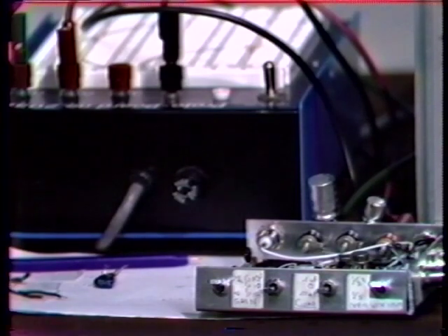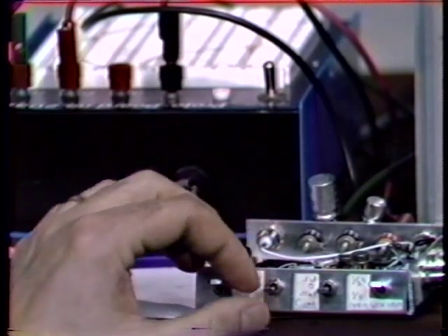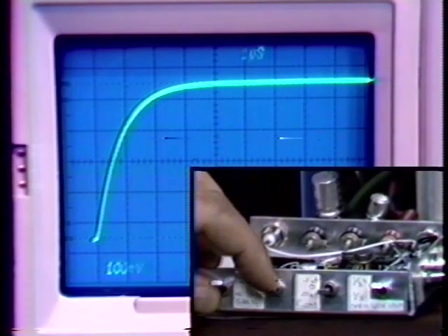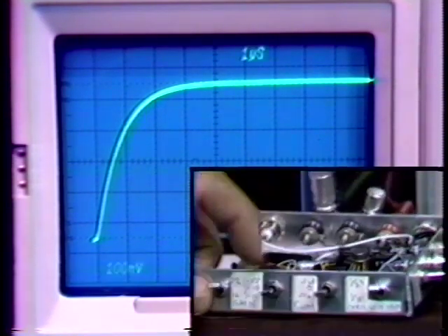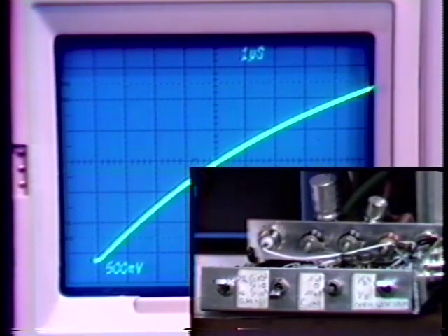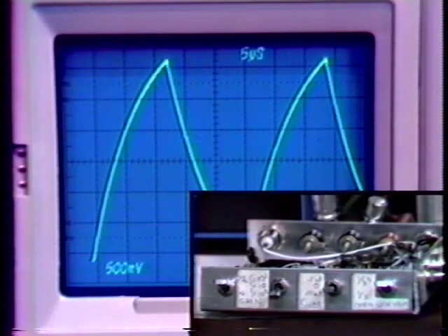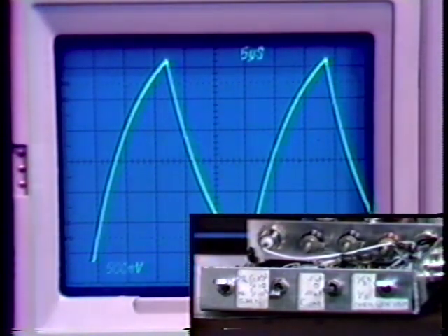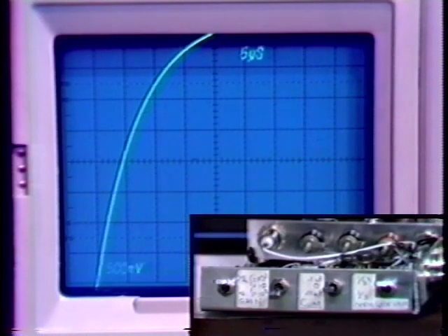And now up the gain by another factor of 10. If I throw this switch down, we get a closed loop gain of 100. We make f 1/100th. Let me do that. And again, I have to change the vertical scale on the oscilloscope. We find out now the bandwidth is so deteriorated with the original value for the capacitor that we have to slow the signal generator, so that we reach final value.